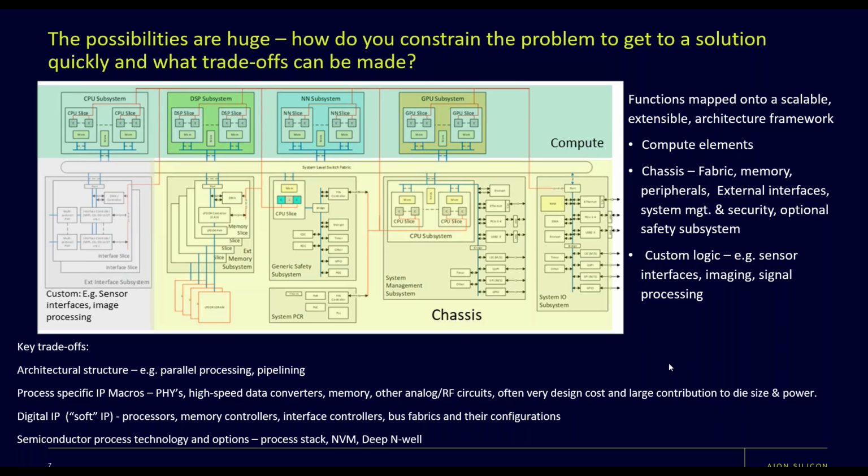So there's a system management subsystem that takes care of things like the boot mechanisms, may provide some of the security features, may even engage in some of the power management, switching power modes. Then we have subsystems to take care of the system I/O, how we get data in and data out of the system. And if we need it, there's an optional safety island here that we could incorporate if we have an automotive design. And that's designed specifically to ensure we can meet specific safety integrity levels.